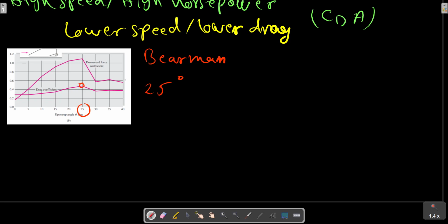For this study, the effect of a moving floor was small, a 10% increase in both drag and lift compared to a fixed floor. It is difficult to quantify the exact effect of geometric change on the automotive forces. For example, changing the windshield shape may interact with downstream flow over the roof, as shown in this picture.